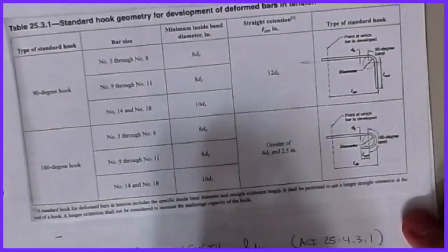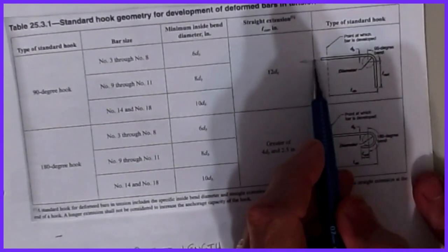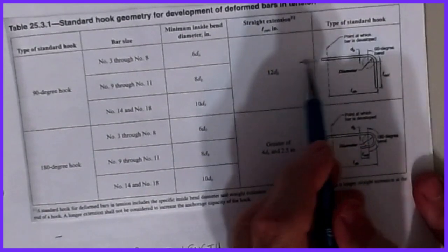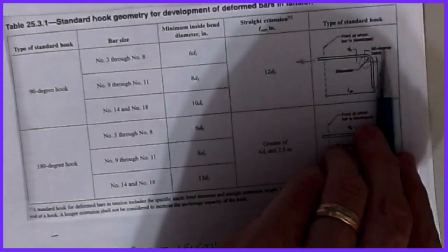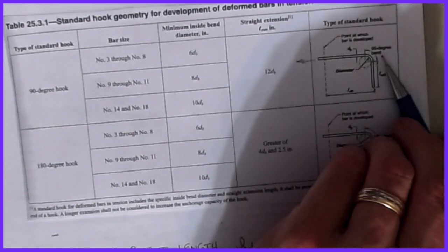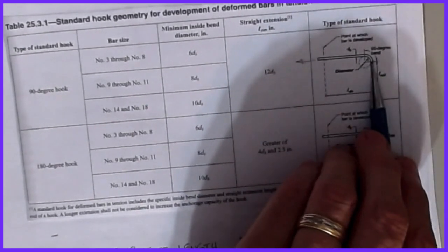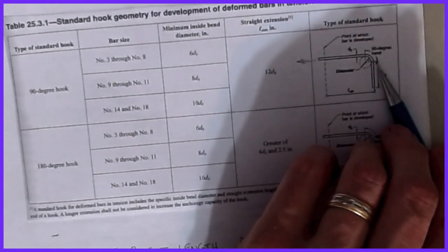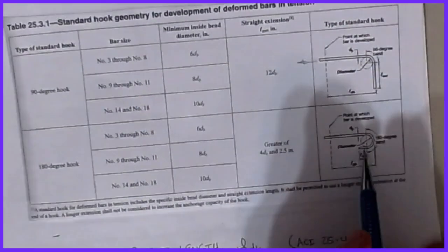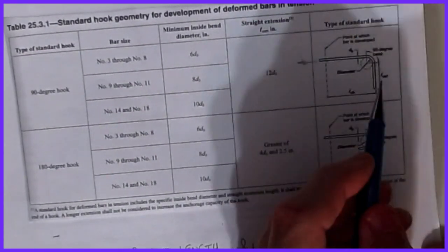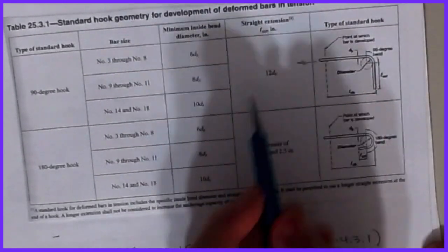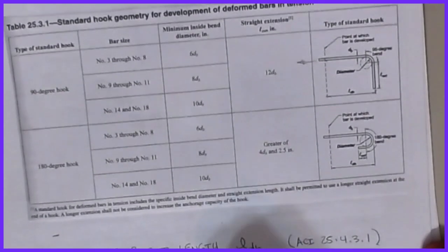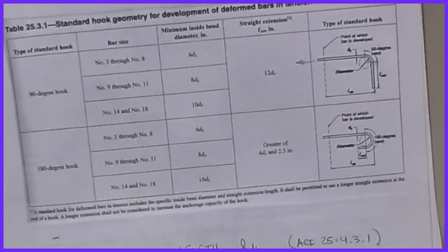The other problem that happens in the 90 degrees is that if I pull on this and this point doesn't want to move, by trying to pull this bar out, this wants to straighten out, and so this end can actually start to pop out a little bit. If you're too close to the edge or have too much cover, that becomes a major consideration, because you don't want to spall that back side off if you're too close to an edge on that back surface. The 180-degree hook doesn't have that, and so they found that by making this a certain length, 12 bar diameters, that problem is generally not as likely. You have enough constraint, or you lower the concrete stresses enough, that it doesn't want to fail or pop out.